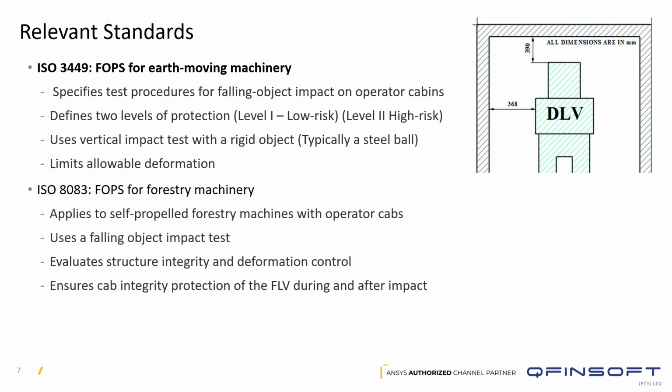This uses a vertical impact test with a rigid object, typically a steel ball, and limits allowable deformation into that deflection limiting volume where the operator will be.